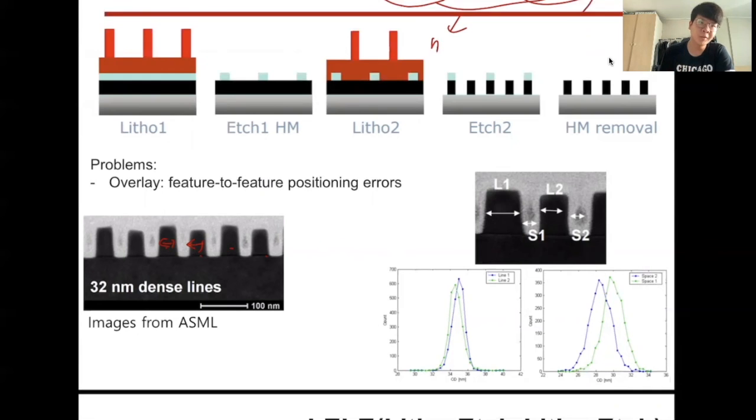In FinFET, we use multiple fins to give more current, for a better swing. So there is a capacitance in the area between the fins. These capacitances are equivalently connected in parallel if we use multi-fin structures.